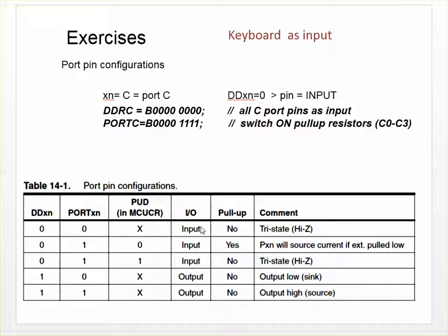As you can see, there are three input mode possibilities. What is the difference between these statuses? It's the possibility to switch on the so-called pull-up resistor.